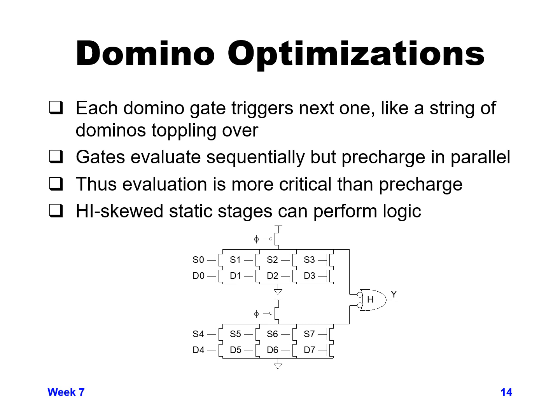So one of the reasons why dynamic gates are called domino gates is it's similar to basically dominoes toppling over. So when the first domino gate evaluates and then goes through the static gate, it tips the next domino gate over and causes that to evaluate, going through its static inverting gate, and then the next domino stage evaluates, and so on.